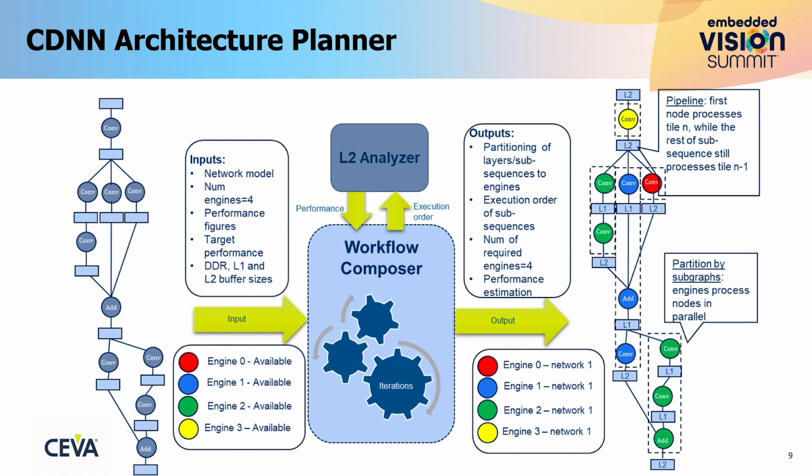We use coloring just to distinguish between the cores. What you should pay attention to is that the algorithm has a strong preference to run in sequences, meaning that we don't do any context switches unless it is absolutely necessary. Also, the buffers between the consecutive layers are marked L1, which means we don't go out to external memory.